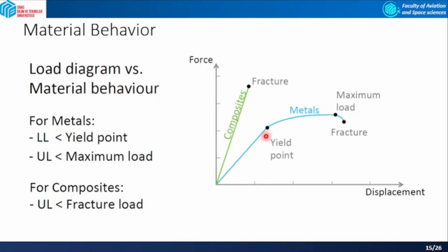But if it goes into the plastic region, when you apply a higher force, you will have such a displacement that it cannot go back to its previous value. So you have some point called the yield point, and the force that is applied is called the yield stress.